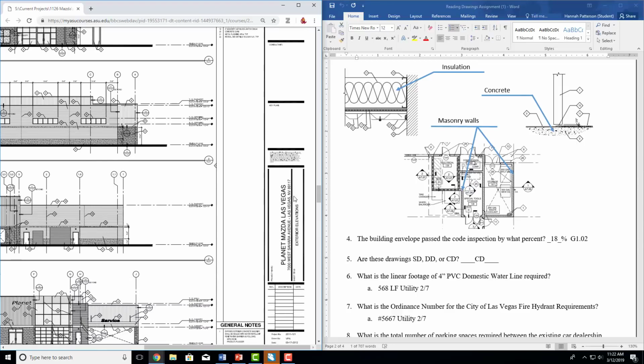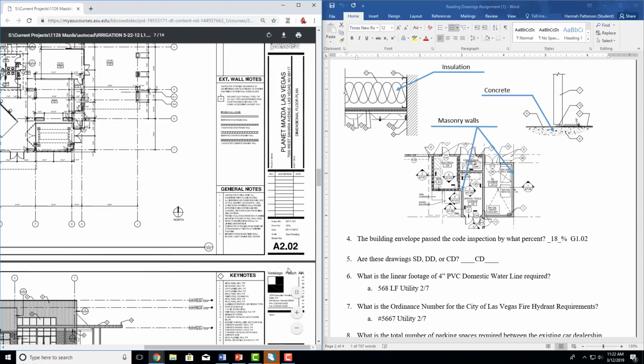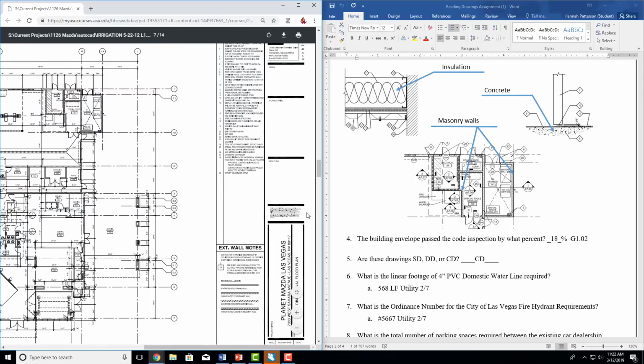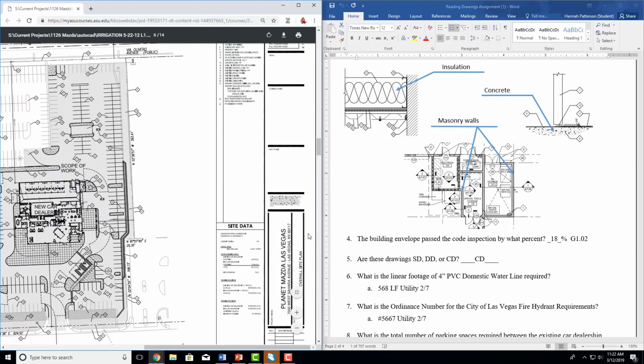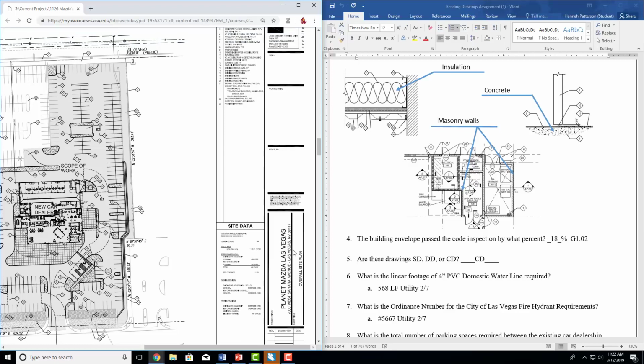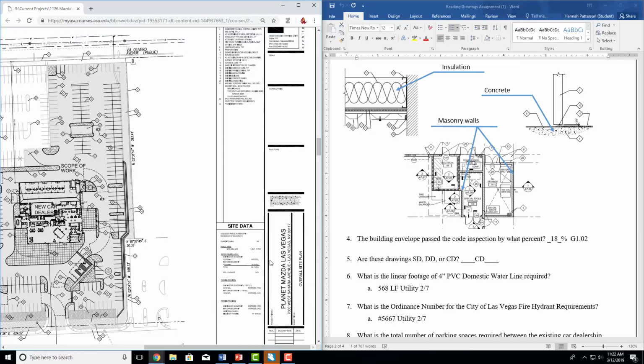So these are your exterior elevations. And sometimes this will be down here, so it'll go A2.02 dimension floor plan. It depends on the drawings, but that information will be somewhere on the right. Usually it's a disclaimer or a note or something, and then a logo will go in the top. This might vary a little bit, but if you need to know something along those lines, that's what this is. It makes it very easy when you're flipping through pages to find the one you want, which is nice because you know it's always going to be on the right side. So we're going to keep going.